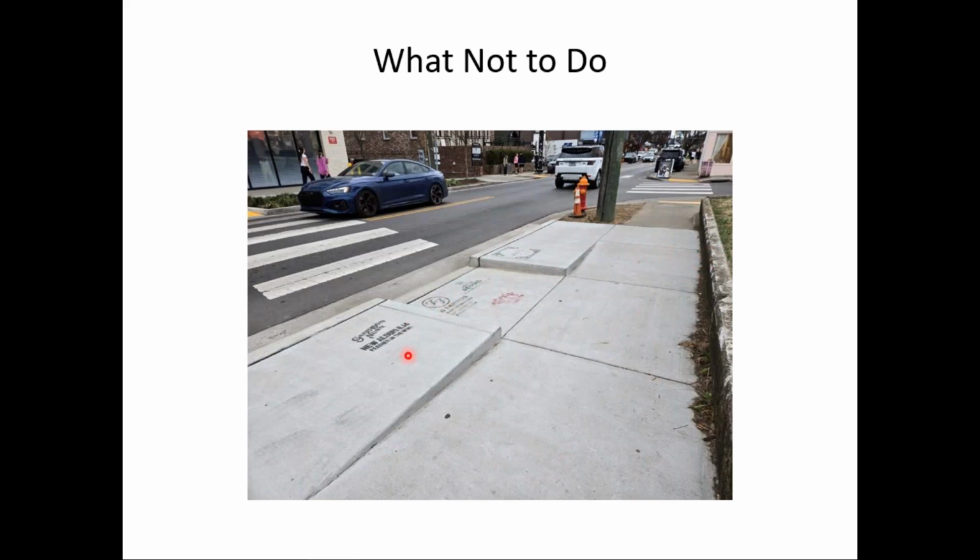So this curb ramp is in the pedestrian circulation path, but yet they should have used flared sides, but they have vertical curb returns. And what concerns me is this is a real serious trip and fall potential at these situations. Pedestrians don't expect that drop in elevation there. And so I'm concerned this agency may be exposed to tort liability claims where people trip and fall and are injured.